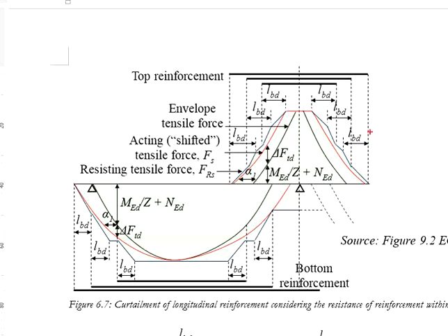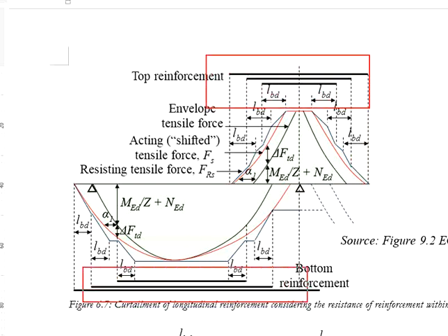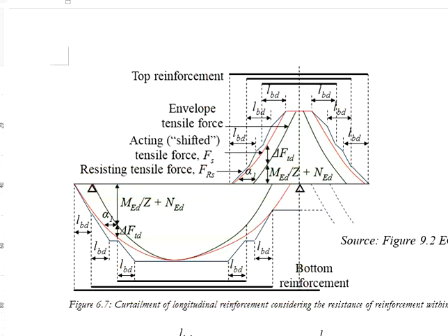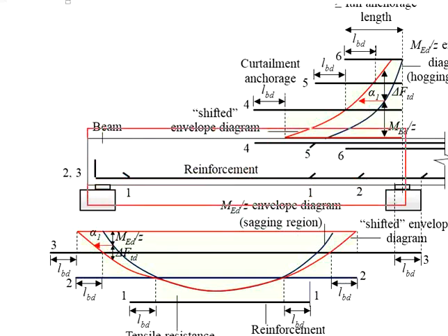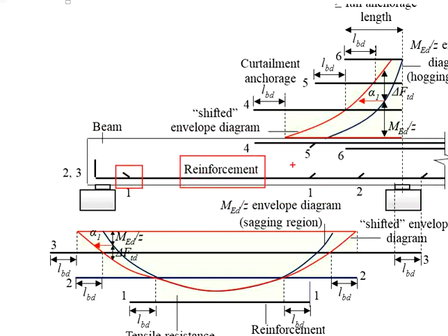And then from there, at the end of the anchorage length, this is where you're going to stop your reinforcement. And then for your curtailment outcome here, you're going to overlay the reinforcement into the beam and start to indicate where the reinforcement bar should be curtailed. Ultimately, it will end up to be something like this, where certain reinforcement may be curtailed at certain specific locations.